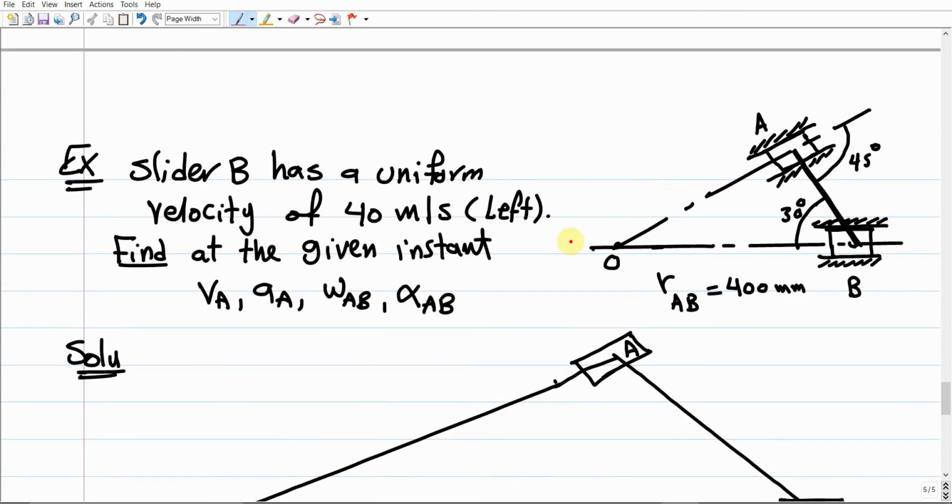I'm gonna use the given drawing to represent the position vectors. And as we agreed, for any slider, we should set up a position vector, and this position vector should go in the same direction of motion of the slider. It should be going over the slider motion. This slider A goes in this direction and moves in this direction. So we're gonna have a position vector, and we agreed that it is better to have this position vector going to the slider. And let us give this one as R2 vector.